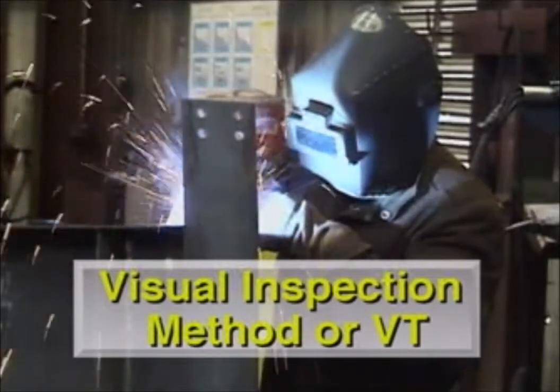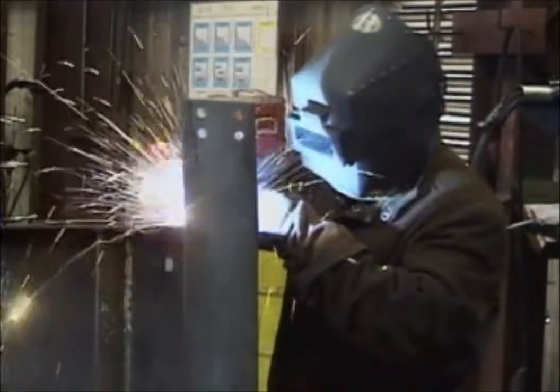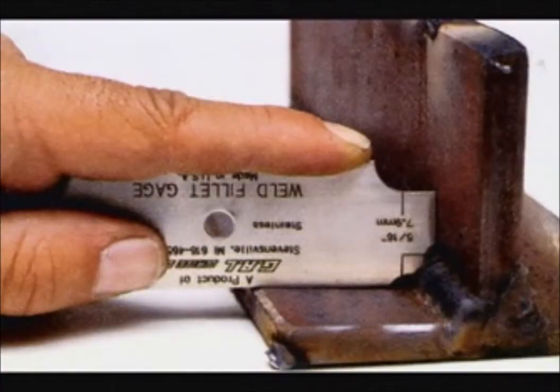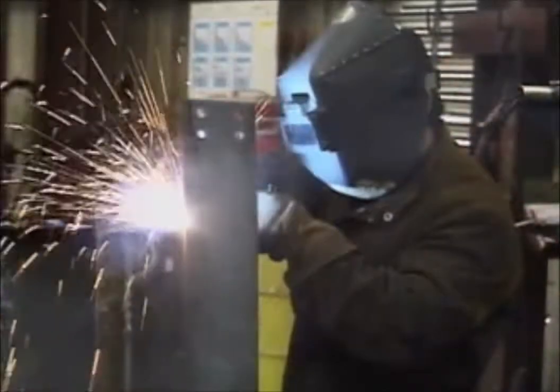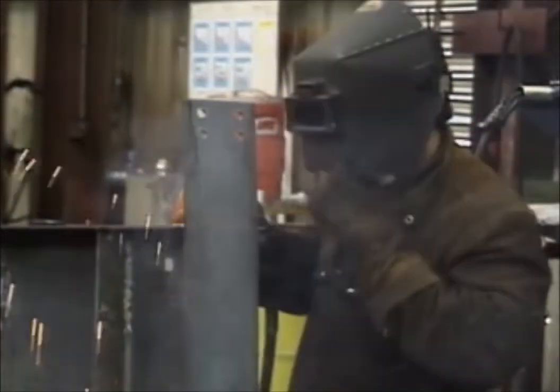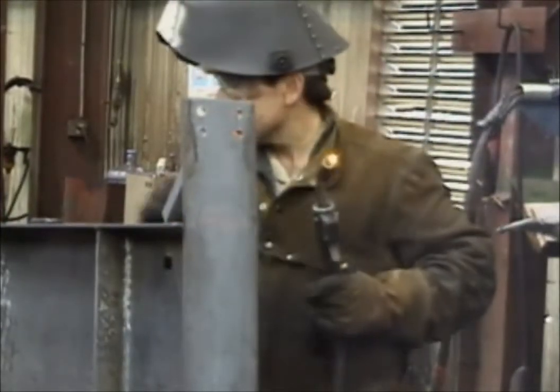The visual inspection method is the most frequently used non-destructive testing method. The majority of welds receive only visual inspection, and it is the only inspection required unless the specification on the design drawings or the steel fabrication drawings calls for a more stringent testing method.